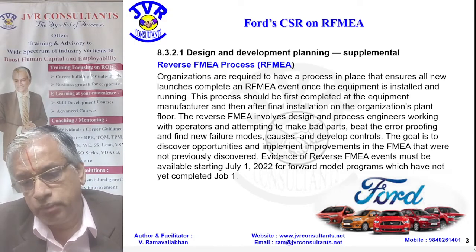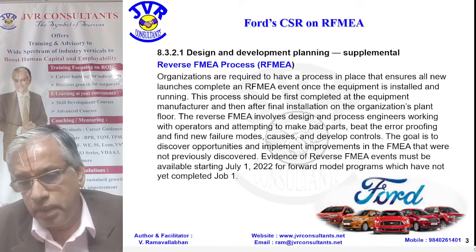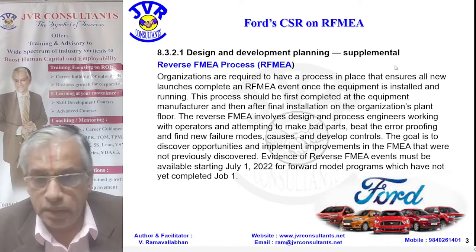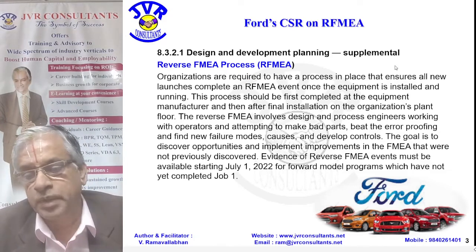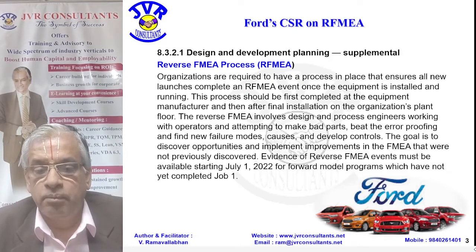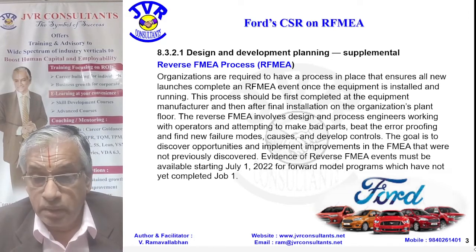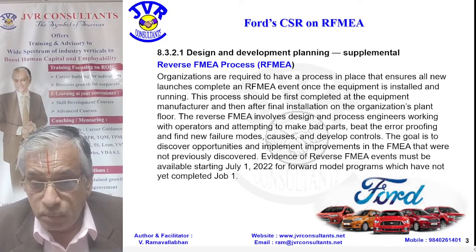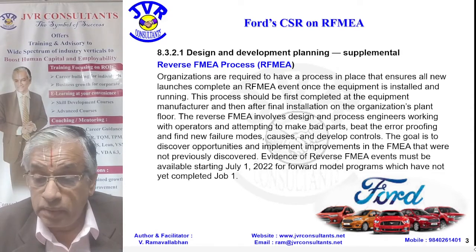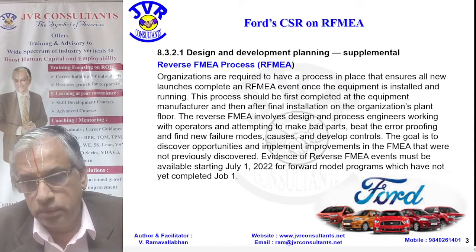When it is running in the shop floor, now we have to go and see. Based on our FMEA, we would have incorporated some error proofing, some detection mechanism, some controls, whatever controls you have implemented in the shop floor, whether those controls are working or not, whether those controls are sufficient or not.